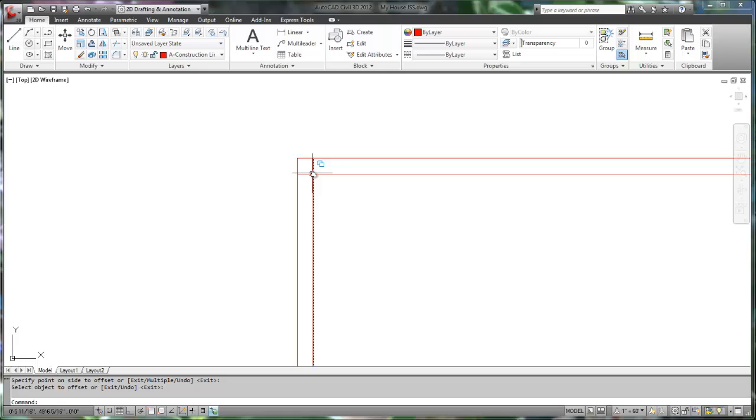Zoom in on the corner of the house. These lines should not cross. AutoCAD has a few ways to handle this. One is to trim the lines, and the other is to fillet. Let's try Trim. The command requires us to select objects.